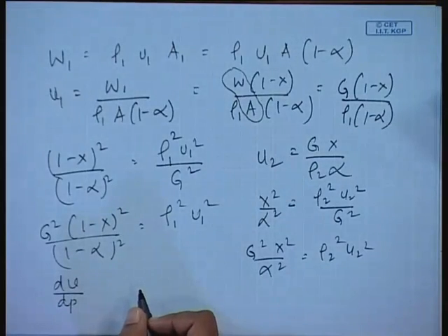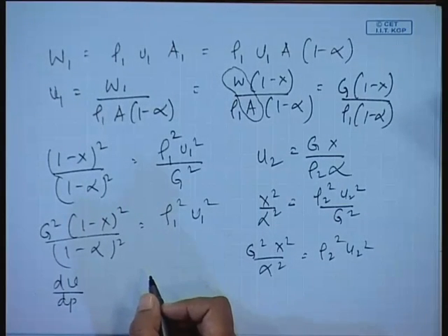What is the basic definition of sound, you tell me? A, for any particular fluid, equals dp d rho, or del p del rho under isentropic conditions. Since here we have very little friction and very little irreversibility, we can consider this to be an isentropic flow, fine.